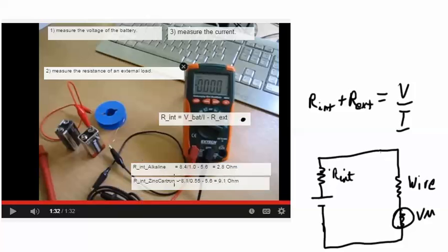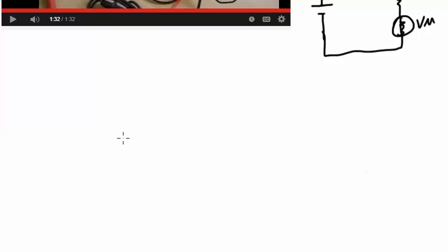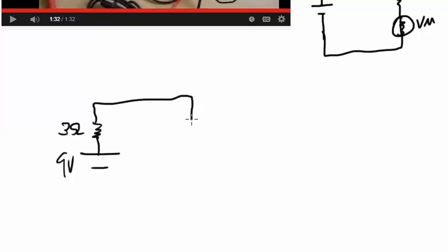At the end of the day, all I was really asking for at the beginning of the video was the resistance of the batteries. I think we were using an alkaline battery, which was 2.8 ohms. So our situation would have been that we had the 9-volt battery and about 3 ohms of internal resistance, and then coming across the light bulbs, which were maybe, well, let's measure those.